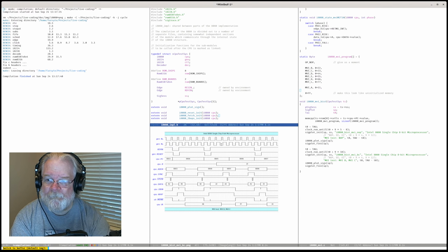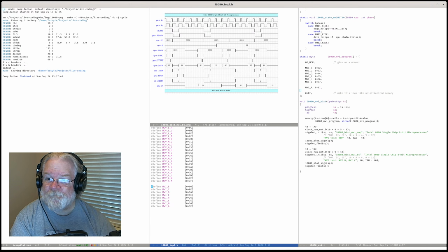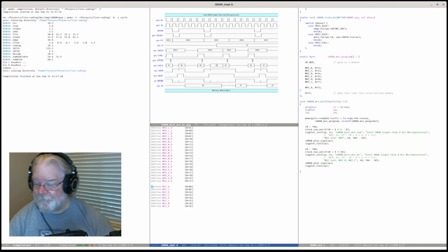So our ops should be a 06 and then a 06 with data and then a 0E. So we get the 06, boom. And then address 4, we get a type 82, and we get data 22. So that's correct. We see the 22 going into B.